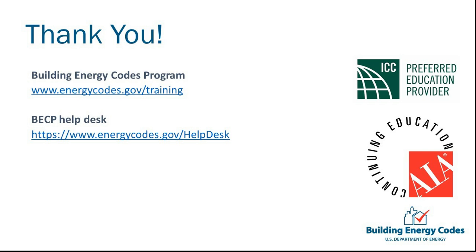would not count. But I will point out that ASHRAE 189.1, which is a green building standard, writes the technical content that becomes part of the International Green Construction Code. They have expanded that. They have a little more freedom in their scope. The first choice is to have it on site, because then you don't have any transmission losses, so you get full credit for that. But you get partial credit if you use a community solar project, for instance. Like my hospital system here in La Crosse, Wisconsin, they are energy independent and they're using landfill gas from across the road. That would not count, unfortunately, under 90.1. It would count under some of these green building programs.